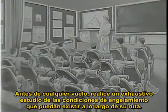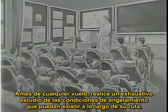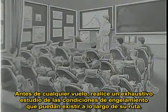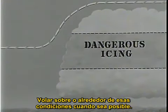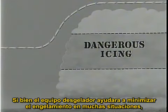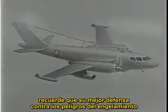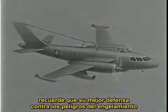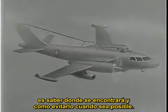Before any flight, make a thorough study with your weather officer of icing conditions which may exist along your route. Never continue a flight into icing conditions. Fly over or around such conditions whenever possible. While the de-icing equipment on your aircraft will help minimize icing in many situations, remember your best defense against icing hazards is to know where you may encounter them and to avoid them whenever possible.